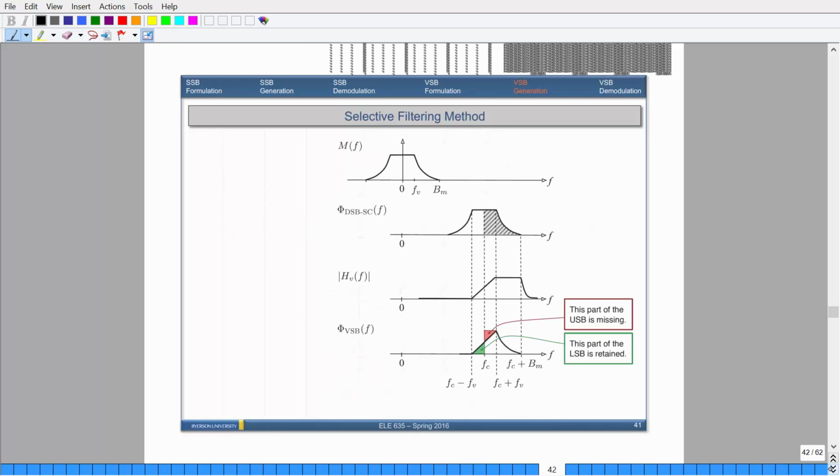Okay. So this is one particular example of what a vestigial sideband will look like. Remember, this here you can think of as the transition phase from before. But now what's going to happen is that we're assuming that there are no frequency holes centered around 0. So if I decided to modulate, remember, this is the same process as doing single sideband. First modulate by your carrier frequency, which is f of c. So this is the positive side only.